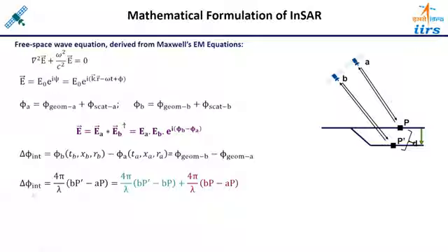So now from this equation we can say interferometric phase is equal to the sum of deformation phase and topographic phase. Okay. So this topographic phase you can calculate from known DEM. Suppose you have the high resolution DEM, so it means the height you know. So from that height you can calculate the phase also. So this particular factor you can calculate from the DEM, and this phase difference you are calculating from the phase of the two signals.